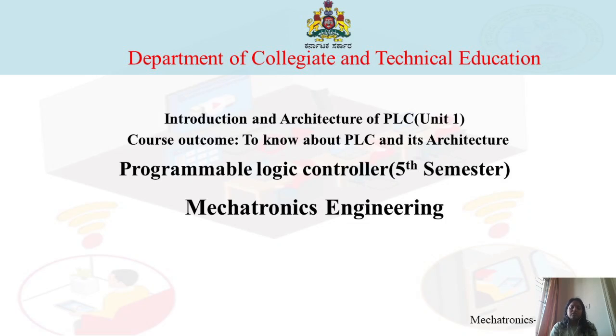Then again, we classified the PLCs based on IO systems and the application ranges. Based on IO system, we have analog IO system as well as digital IO system. For continuous signals, we go for analog IO system, and for digital signals, we go for digital IO systems. And based on application ranges, that is, based on how many input and output terminals we can use, we have divided them into nano PLC, pico PLC, micro PLC, small PLCs, medium PLCs, large PLCs, and very large PLCs. Based on the IO devices required for your application, we select the PLCs.